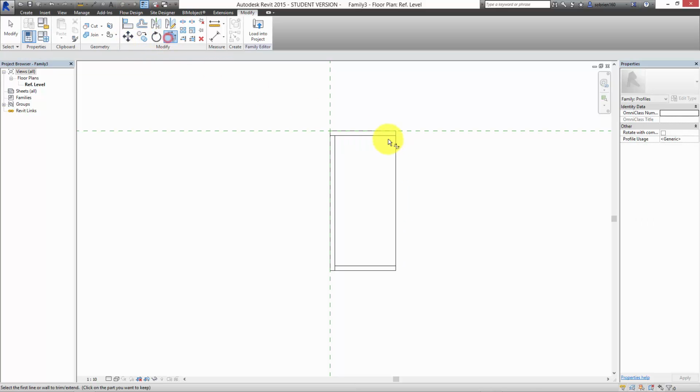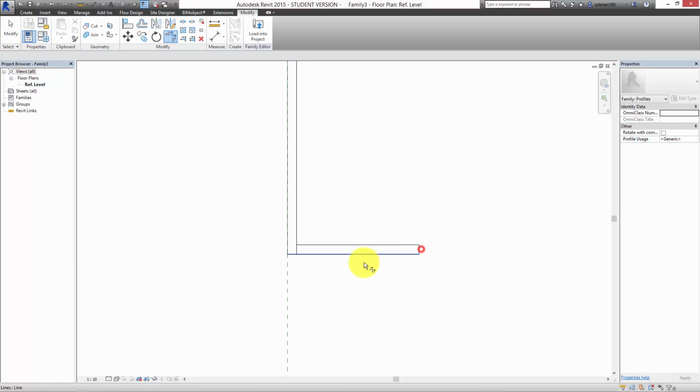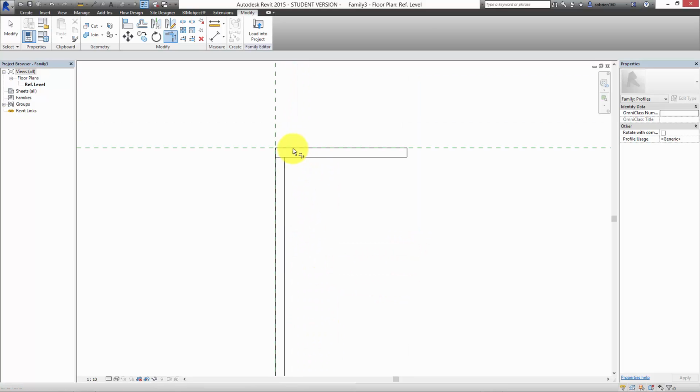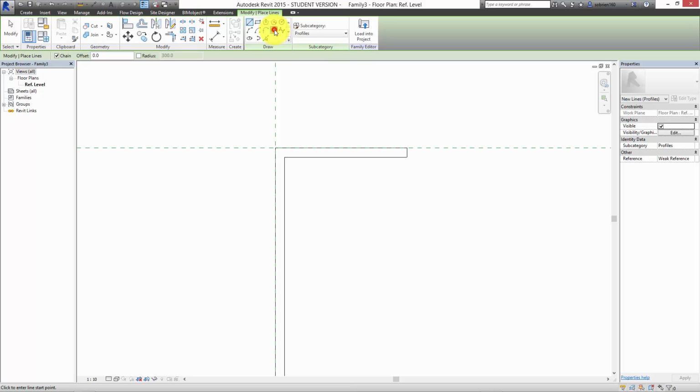I'm going to use the trim button. Trim here, trim here, trim here. And just for the hell of it, let's also give it that curve again. So I'm going to give it a fillet arc, because the reason I'm giving it a fillet arc is that if you're doing a rendering, it adds so much quality to the image if the curves are reflecting light in the steel sections, rather than just leaving it completely straight. So let's just say 10 mils, 10 mils,